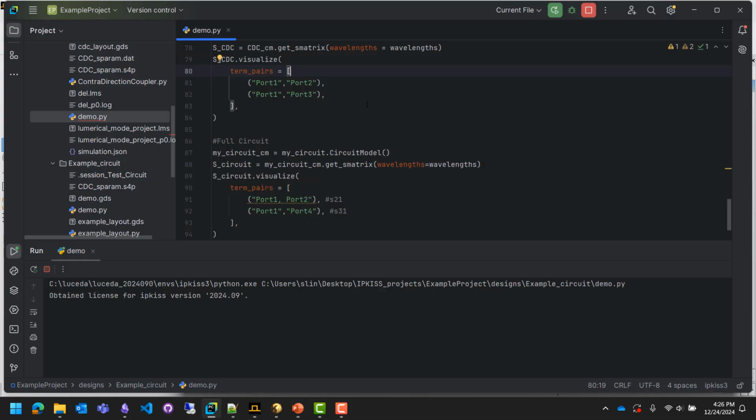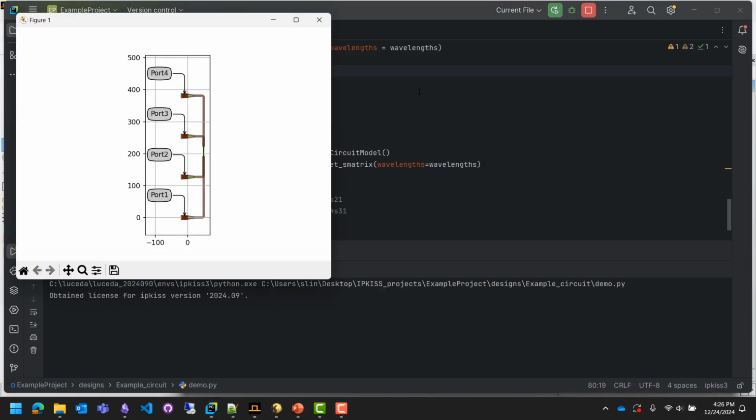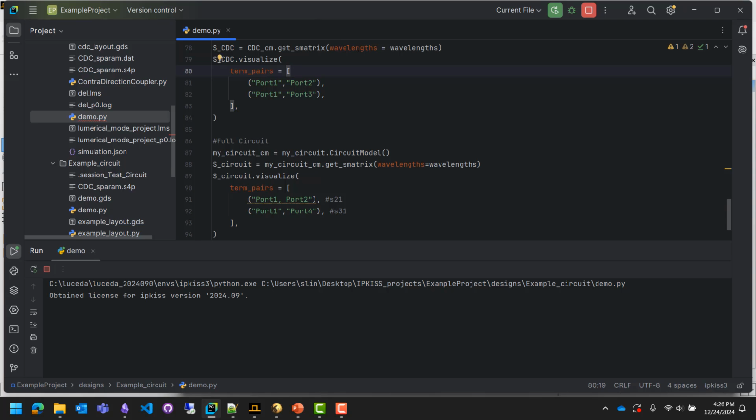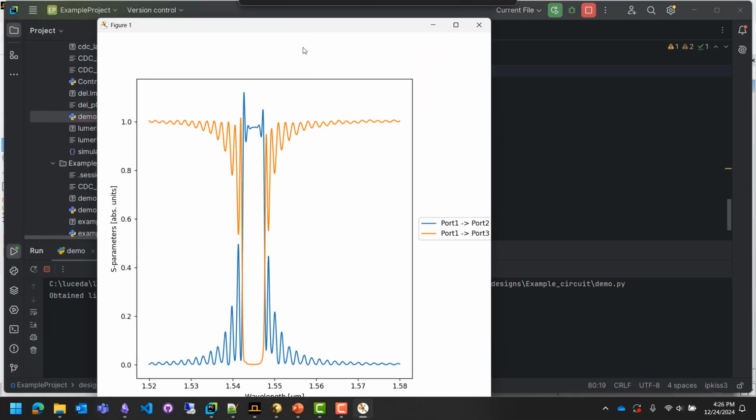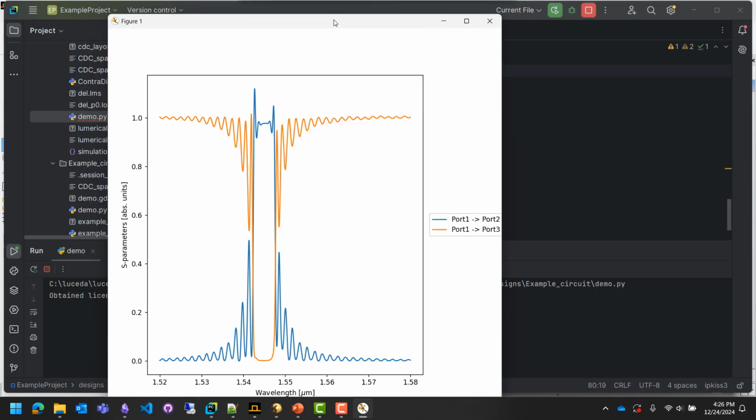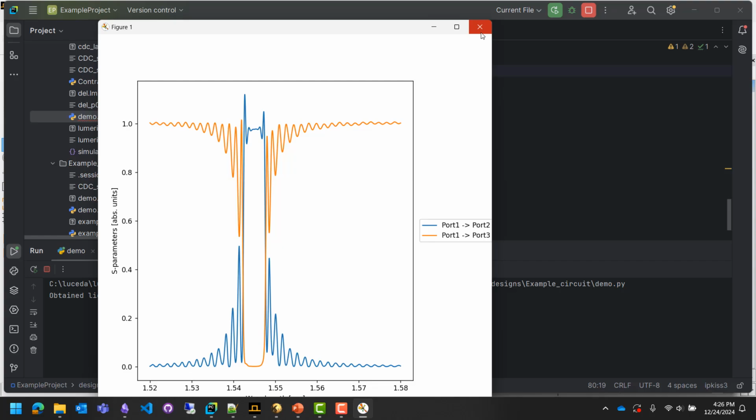The filter response should just be the same as we expected and saw in the previous part B. So nothing fancy. It's reading from that S parameter file. And you'll see it's a bit off here. The reasoning is because it's extrapolating because we gave it more points. There's an easy fix to this, and I'll showcase it in a bit, just so we can make sure that the transmission is proper and reasonable. But this also comes because our simulation didn't put enough wavelength points into it, while we're asking for a higher amount of wavelength points.